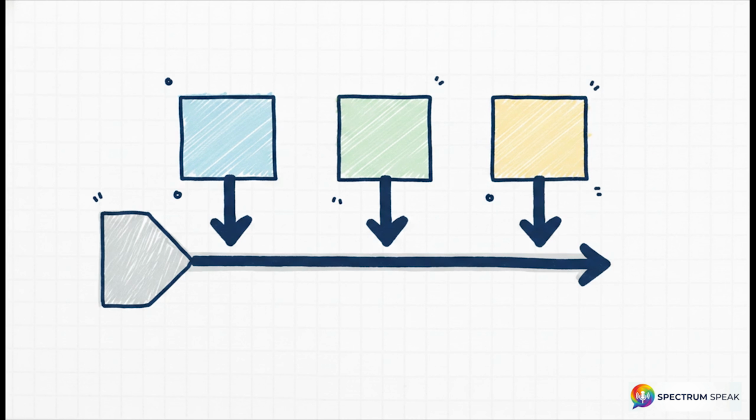When we calculate the voltage at point A, which happens to be the ground connection for Circuit 1, the equation reads like this. V_A = (I_1 + I_2 + I_3) × Z_1. Now, why is the math structured exactly this way? It's because the current from all three circuits has to travel back through that very first impedance segment, Z_1, just to get home to the ground point. So the crucial takeaway here is that point A is absolutely not at 0 volts. It's being lifted above 0 by the combined current of every single downstream circuit.